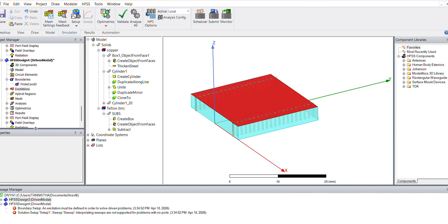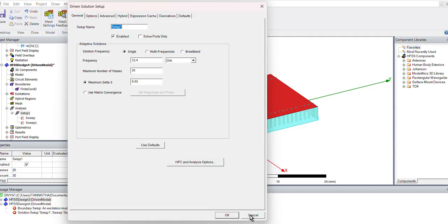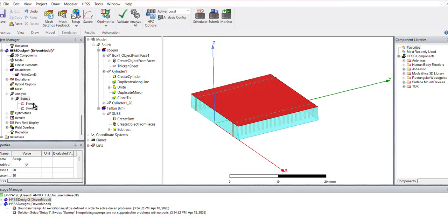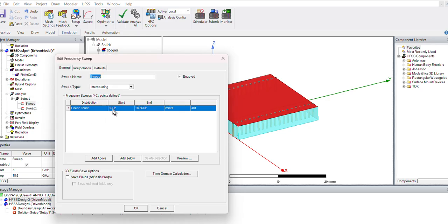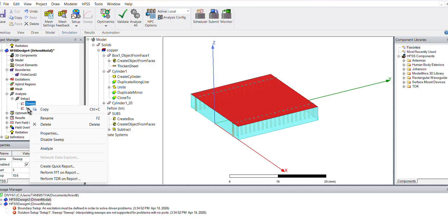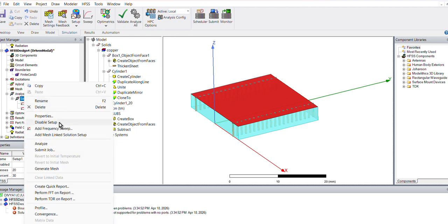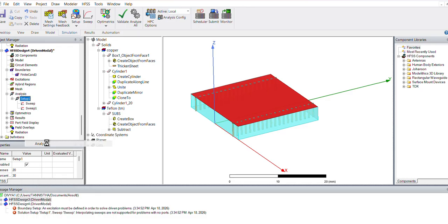We know it should work from 8 to 12 gigahertz and everything. And now let us see. First validate. Now let us go for analysis and setup. Our setup is already there, the earlier setup from last day. Because our design is still 8 to 12 gigahertz, we can stay from 3 gigahertz, but it doesn't matter because it will be much higher. So let us keep that. Let's see what is happening. And now we run this thing. Go to setup and analyze all.